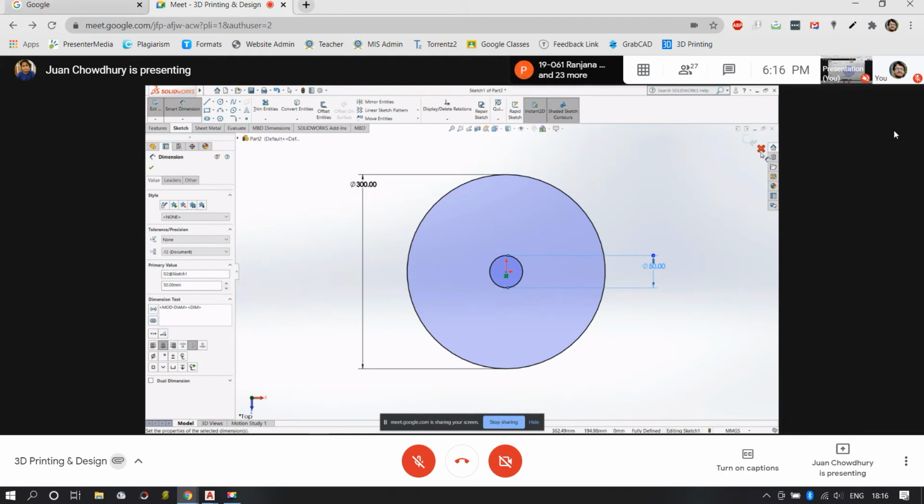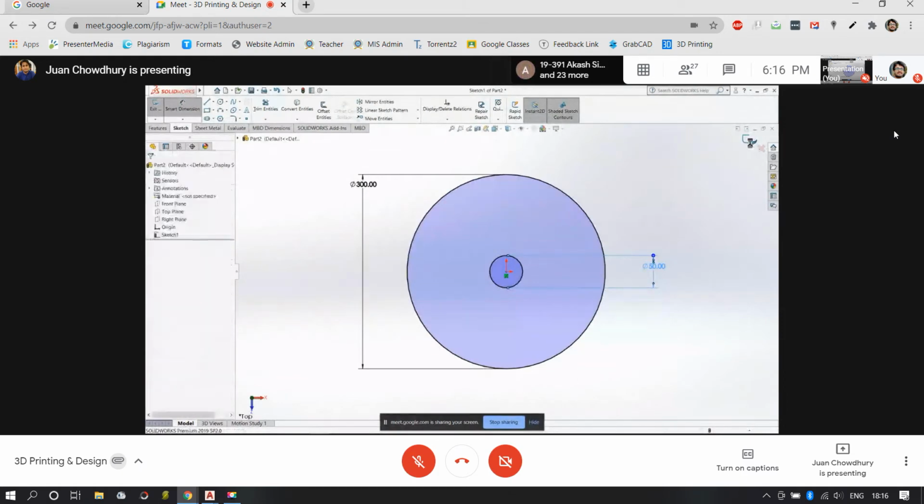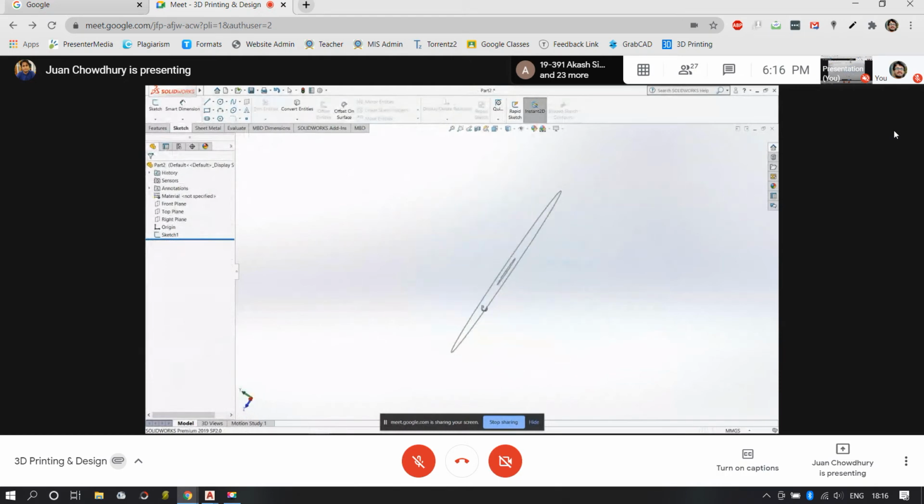There's a cross. If I click on the cross, the whole sketch will get cancelled. It asks whether I want to discard the changes, and if I do so, the entire sketch will be erased. So I'll just exit out of the sketcher, and you see two small lines that have taken place. Now it might seem a little inconvenient that I have not laid out any grid. In most cases, we do not lay out any grid, because the dimensioning feature is really flexible in this system.